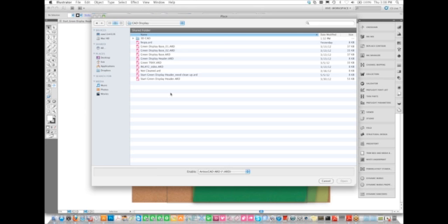Once I have the structural design within Illustrator, I can open up my studio window. And this studio design window is a plugin of Esko on top of Studio. Now you can see that indeed I have this background panel, but I can see that some elements of my graphic design need to be added onto my structural design. Okay, now how do we do this? I have prepared it a little bit, but just by selecting these line works, now I can say, okay, I'm going to export the selected object back to the ArtiosCAD file.